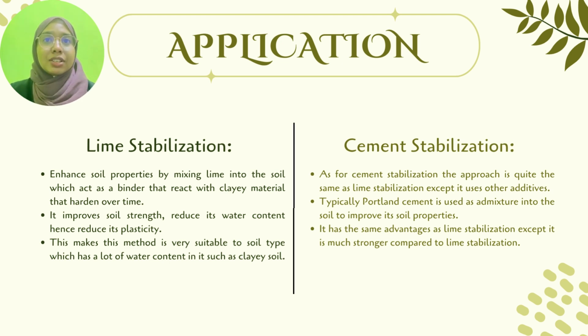Cement stabilization is done while the compaction process is continuing. During the compaction process, they use some amount of cement. Soil particles contain void space. By that means, the cement fills the void space of the soil easily. So, as a result, the void ratio of the soil may reduce.